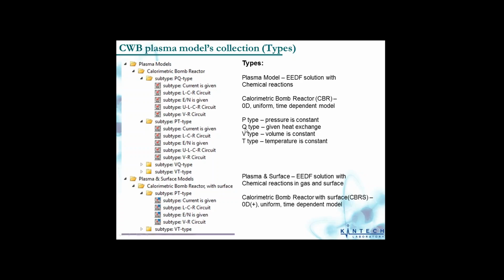And also another calculation, adiabatic calculation. It's the opposite of the case of constant temperature. Adiabatic means that, for example, energy released due to the chemical reaction will lead to an increase of the enthalpy of the system. Also, there is a possibility of varying the heat exchange between this reactor and the surrounding media, if you know it.